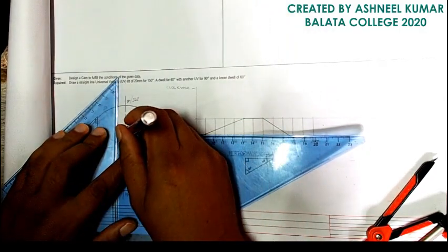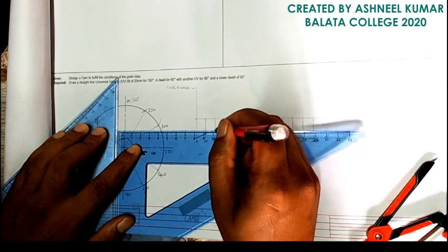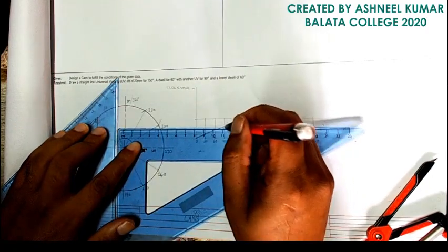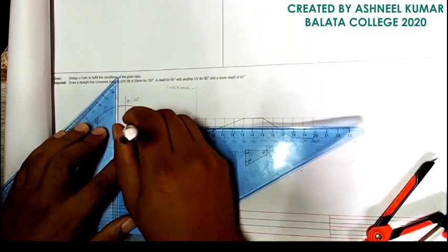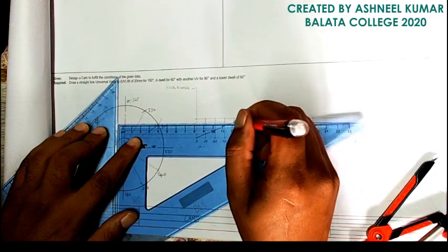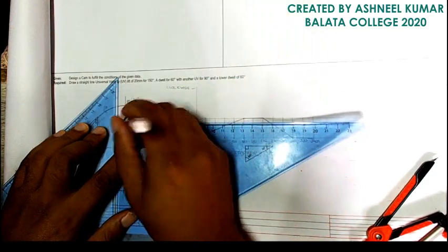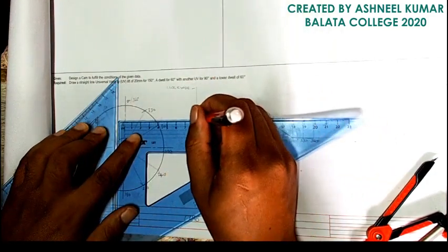So you are going to take all those points horizontally across to the center line of the circle that is there. We'll draw it for the first half of the cam, then we'll look at the next part of the cam.